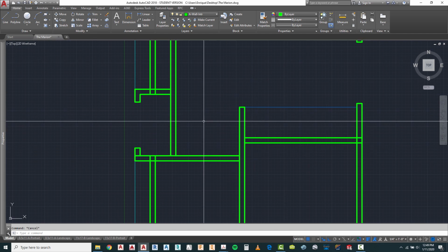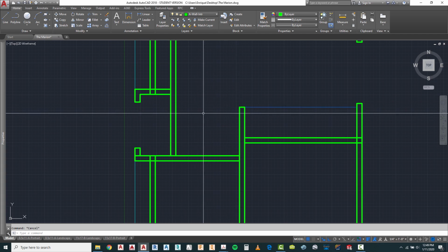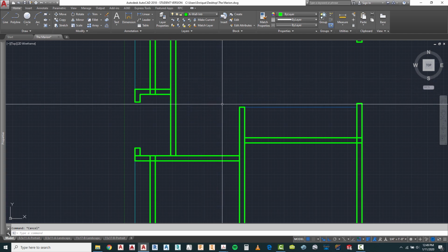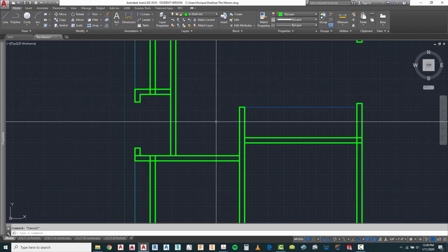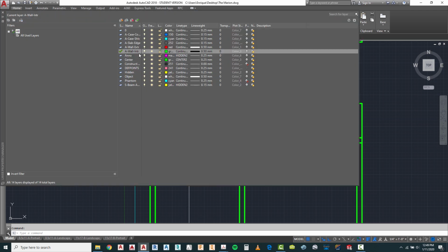Now what I want to do is make sure that I have a deep enough shower into there. One of the things I need to do is to draw a curb. Again, this is not going to be a real door in here. It's going to be part of a shower enclosure. Typically you do a 4-inch step up across. So I'm going to go ahead and create a new layer for that curb. Now I've got a wall interior here. It doesn't really matter where you're at as long as it's not set to one of the no plot layers.